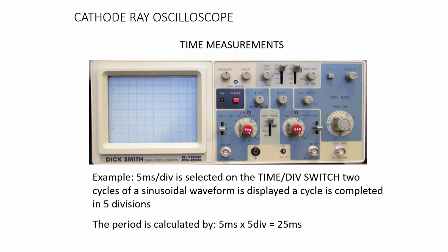Next, volts per division control. This controls the amplification or attenuation factor of the vertical amplifier or attenuator. When adjusted, it changes the height of the wave on the screen. So small signals or large signals can be easily and comfortably measured using the CRO, by putting the volts per division in different positions so that it is comfortable for us to take the readings. It must be not too small, not too large.